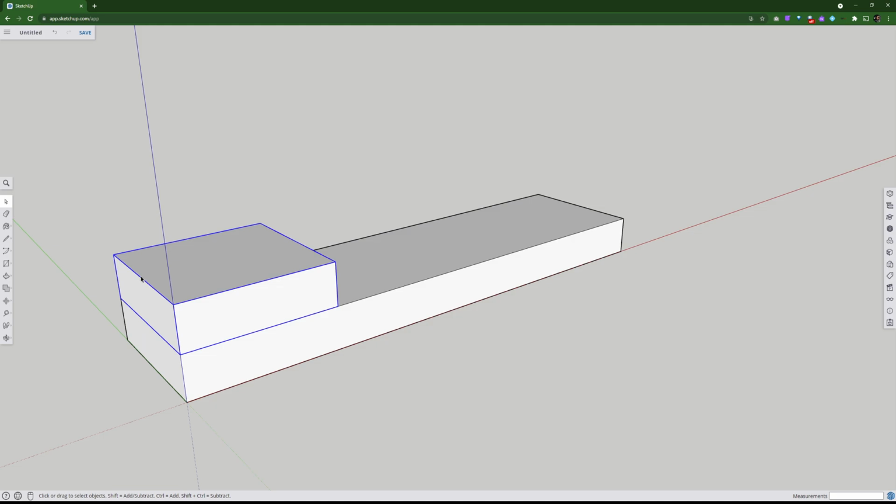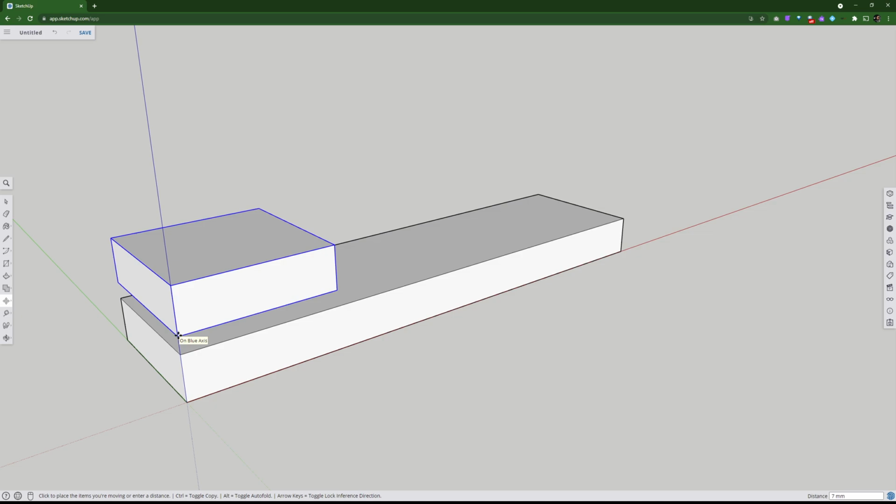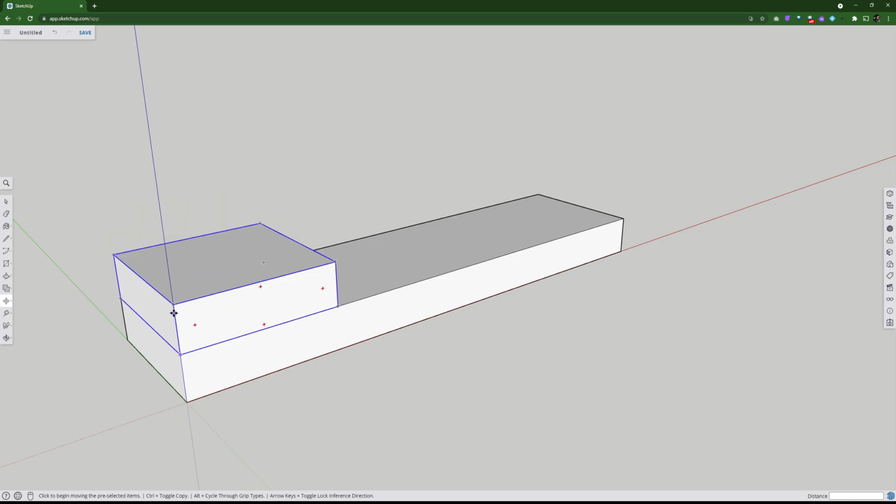Now we put two layers on top of each other. So there's a second layer up here. I'm going to use this component and duplicate it. There's no point drawing another piece because I want to make it quick. The idea of CAD is that it's quick and accurate. So what I'm using down here, fourth from the bottom, is called move. It'll be on rotate if that was the last tool you used, or it could be on scale or whatever. But we want to change it to move. So these are 4 arrowheads, a crosshair type thing.